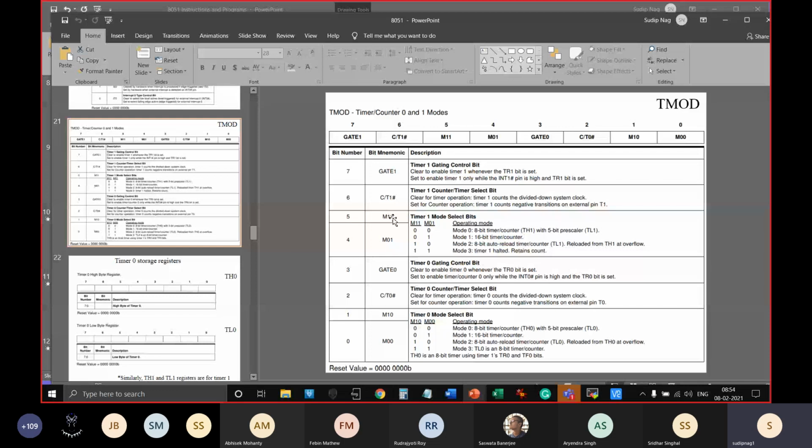Once TL overflows after a certain time, TL gets copied again from TH. So TH keeps a copy of the data such that every time the overflow condition happens, TL is updated. Every time the bit duration elapses, you copy TH to TL and start counting in TL. That is the meaning of this particular configuration in timer 1.